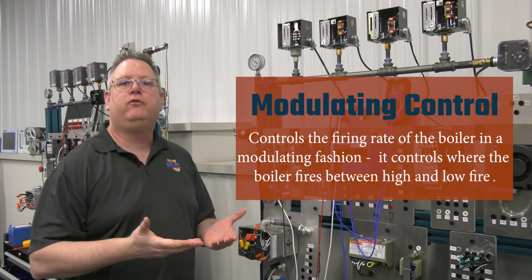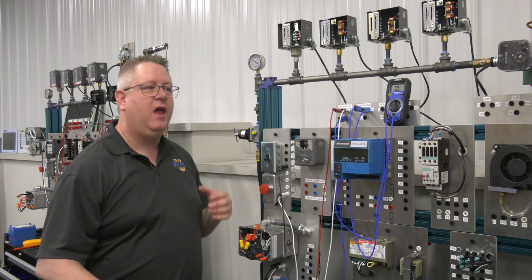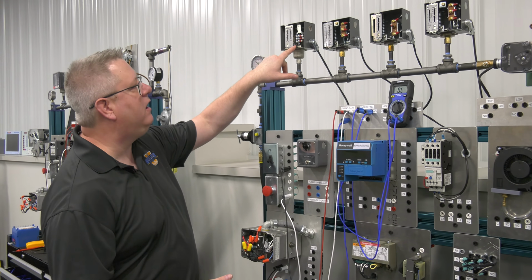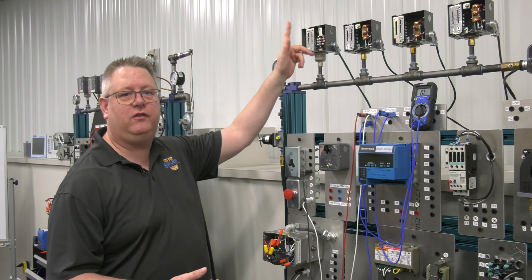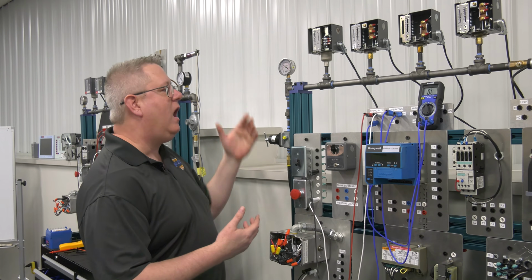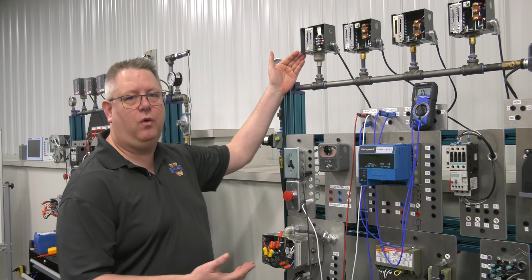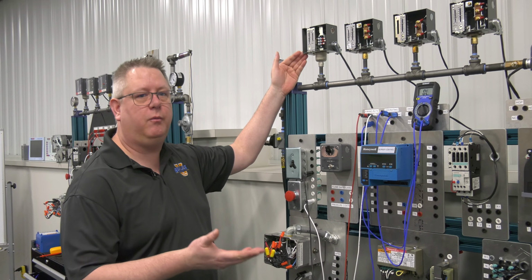So it controls where the boiler fires between high and low fire. And the way it does that is by using a bellows that is going to drive a wiper across the potentiometer. So I like to discuss this control first because it's actually the one that's doing the majority of the work in controlling the pressure of the boiler.